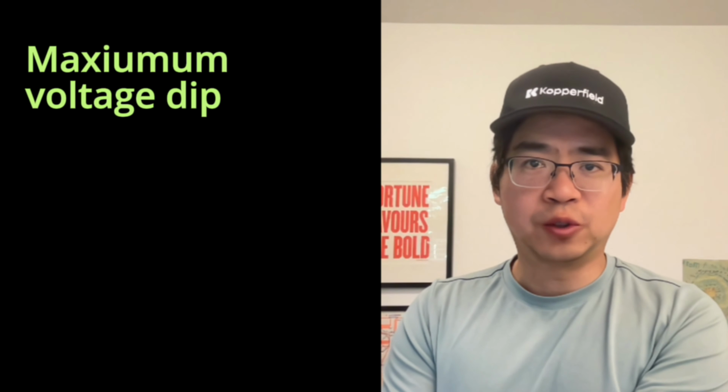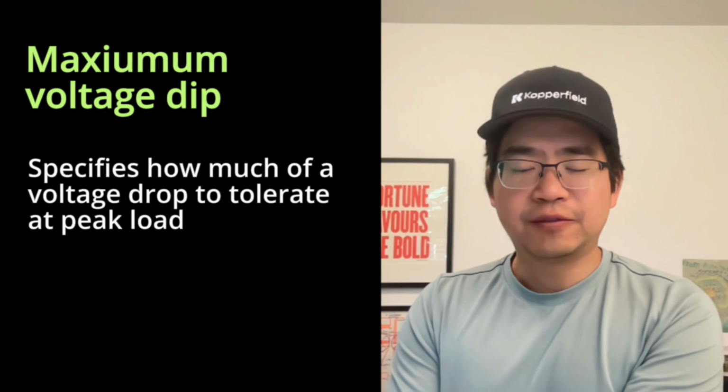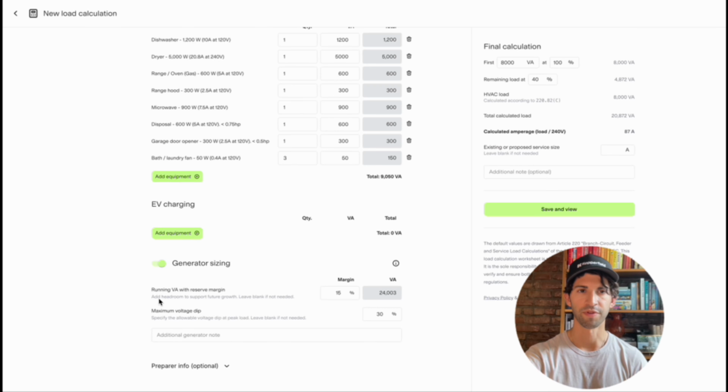Now there's the maximum voltage dip, which lets you specify how much of a voltage drop you're willing to tolerate at peak load. For this project, we'll stick to the standard residential voltage dip requirement of 30%. With a 15% reserve margin applied, our running load comes out to 24 kVA, which you can use to choose which generator will be suitable. In most cases, you can convert kVA to kilowatts directly, since residential generators are often rated at a power factor of 1. That said, it's not always guaranteed, so it's always worth checking the manufacturer's specs if you're recommending a specific model. You can use the notes field to record any sizing decisions or context.